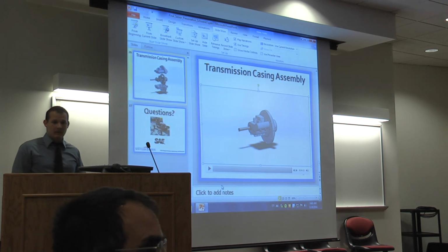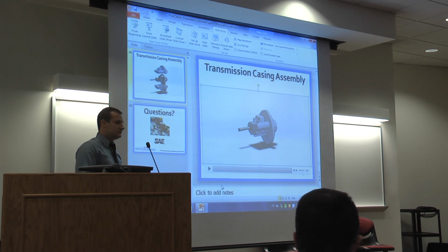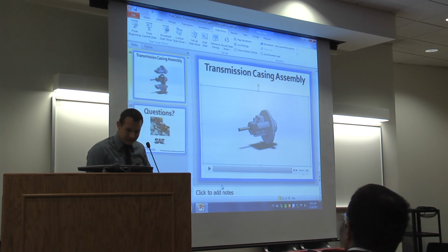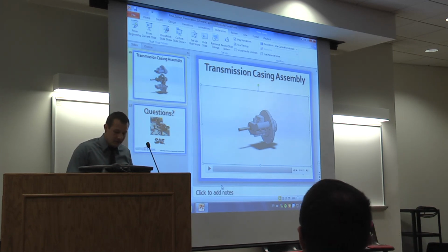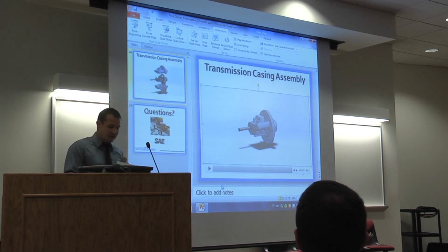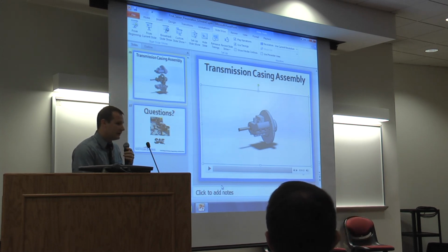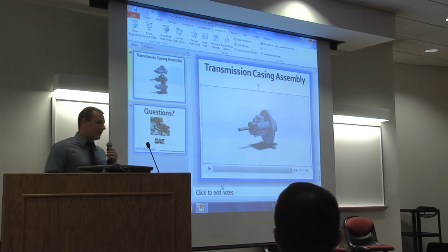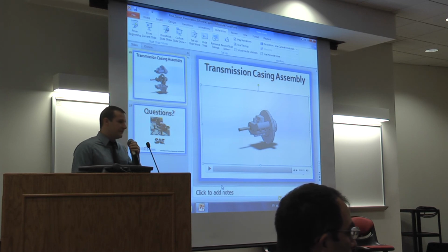Okay, thank you. Any other questions? Actually, do you mind? You analyzed the factor of safety, so from a strength perspective, it looks fine. How does aluminum do in fatigue? That is a great question. Looking at an SN curve for fatigue analysis, with a cyclic loading for this transmission casing at 10 to the 6 cycles, it would require around 200 megapascals of stress for the casing material to fail. And within this FEA analysis, the highest amount of stress that acts upon the casing is around 1.3 megapascals. So we're way under that fatigue stress.